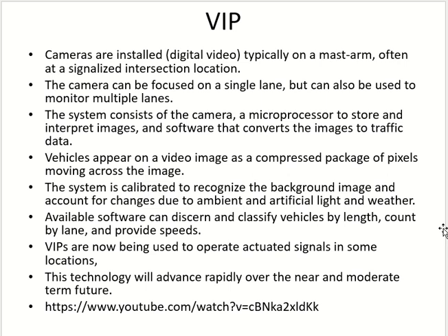So the location of the camera is very important. To establish this system, the first thing you have to worry about is the location of the camera. The best view is the one from the top front. The camera should be somewhere on the top, looking at the road from the front, not from the side. If you have a pedestrian bridge, for example, you can put the camera under the pedestrian bridge with the beam or with the column. The other bridge as well, the concrete bridge, you can put the camera with the pier of the bridge.